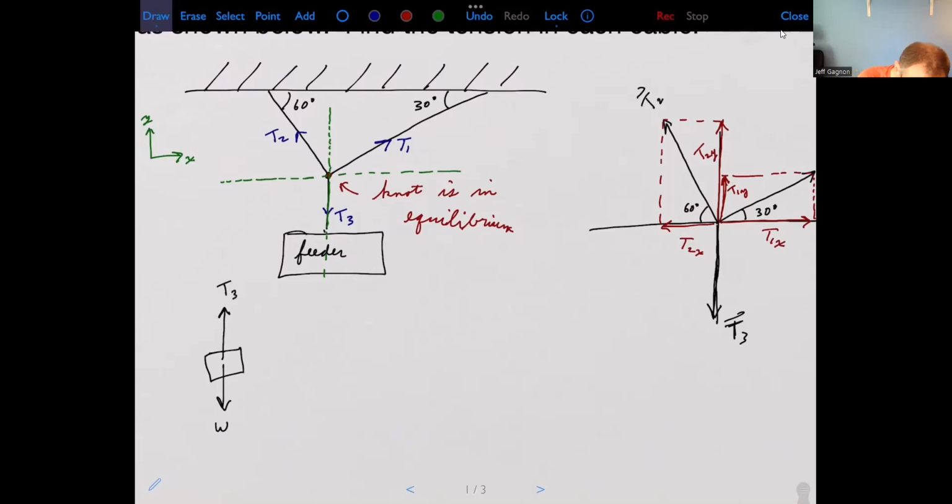Okay, so if I choose a coordinate system, which I'm just going to use my standard XY coordinate system here, there's no forces even acting in the X direction. I'm not going to worry about the X direction, but let me apply Newton's second law to the Y direction. So I have the sum of the forces in the Y direction is equal to 0. Remember, it's in translational equilibrium, so the sum of the forces is always going to equal 0. So in this case, I want the Y component of T3. I want the Y component of the weight, and that's got to equal 0.